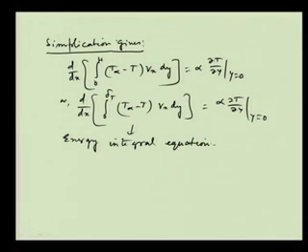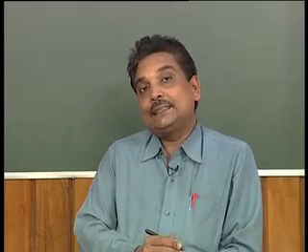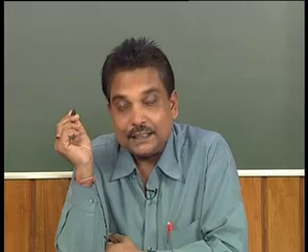What we will be doing is assuming some standard temperature profile and some standard velocity profile for the boundary layers, and putting those profiles into the governing equations we have developed as integral equations. Then we will find out what happens to the heat transfer rate or heat transfer coefficient, and to the friction factor.